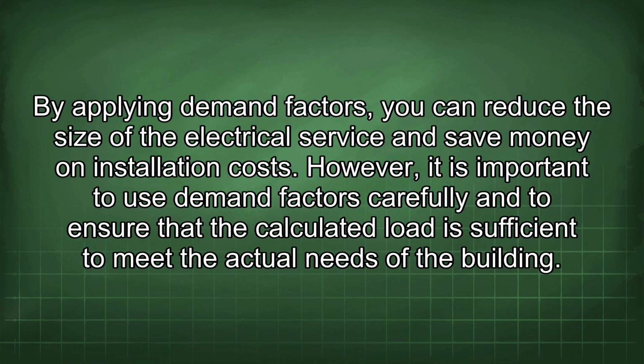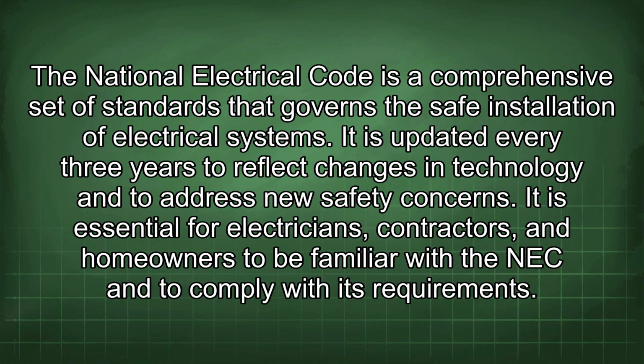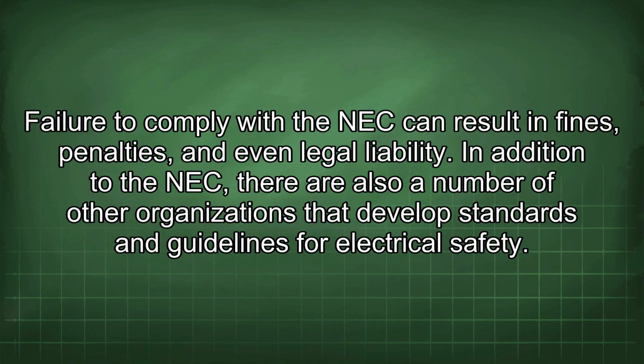By applying demand factors, you can reduce the size of the electrical service and save money on installation costs. However, it is important to use demand factors carefully and to ensure that the calculated load is sufficient to meet the actual needs of the building. The National Electrical Code is a comprehensive set of standards that governs the safe installation of electrical systems. It is updated every 3 years to reflect changes in technology and to address new safety concerns. It is essential for electricians, contractors, and homeowners to be familiar with the NEC and to comply with its requirements. Failure to comply with the NEC can result in fines, penalties, and even legal liability.